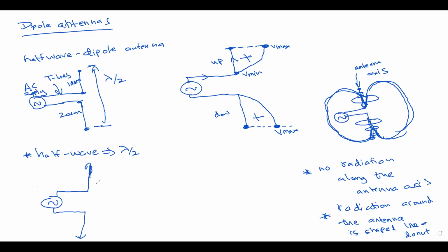The wave pattern generated in this situation will generate voltages in this manner, where the voltage maximum will happen at the end point of the antenna arm, the voltage zero point will happen at an intermediate location, and there's another voltage maximum at the feed point of the antenna.